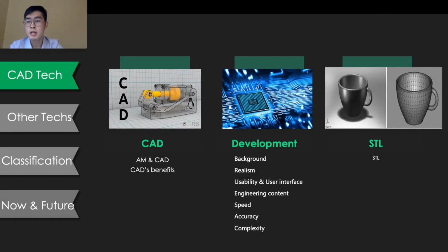The solution is to use the STL file format. It can be accessed easily by all CAD vendors and is now a standard output from nearly all solid modeling CAD systems and has also been adopted by AM system vendors. This picture is an illustration. It uses triangles to describe the surfaces to be built. Each triangle is described by 3 points and a facet normal vector indicating the outward side of the triangle.